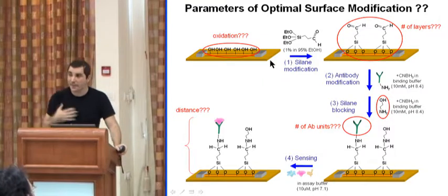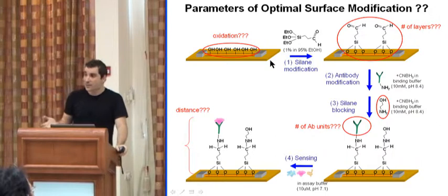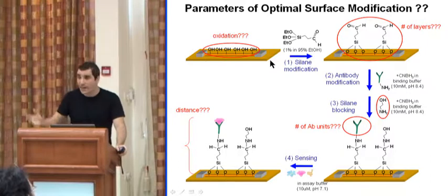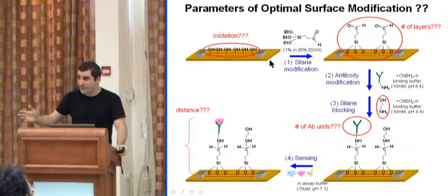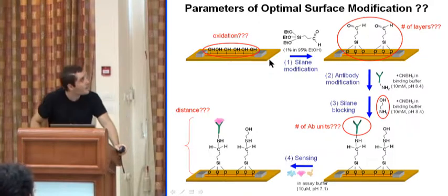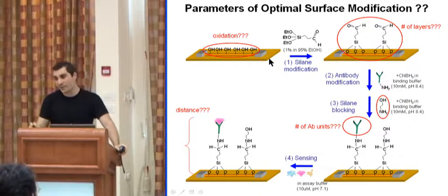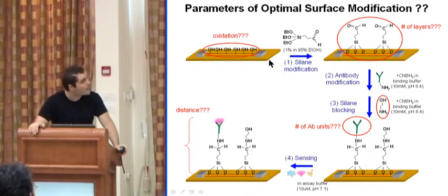Everybody today, including myself, prepares devices on silicon oxide surfaces, so we get chemical modification on all the surface. One of the projects that we are taking on today is to prepare those devices on surfaces different than silicon oxide, such as glass or plastic surfaces, and to be able to do chemical modification only on the silicon nanowire.